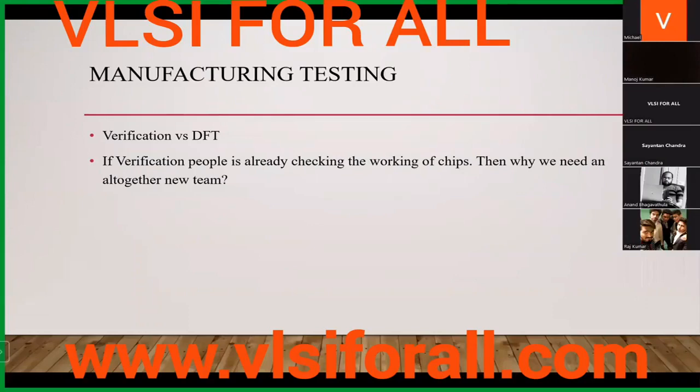I'm saying that in terms of hardware, the extra hardware we are adding, maybe that part. We are adding extra hardware also, right? That is actually making the chip more area consuming, right? Yes. That is actually not a benefit, but a drawback of DFT. We want to minimize the area also. In terms of that idea, DFT will look only at how compactly we insert the hardware.